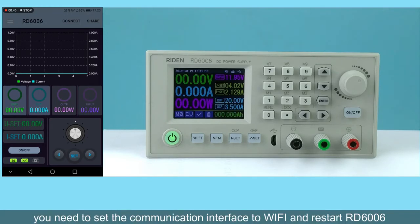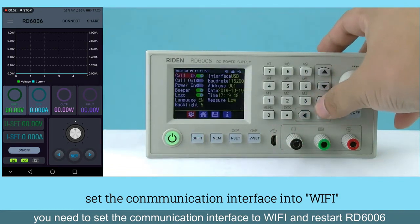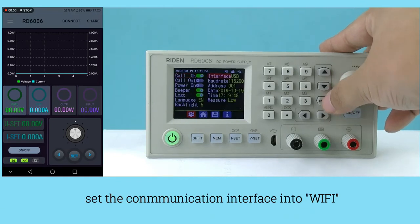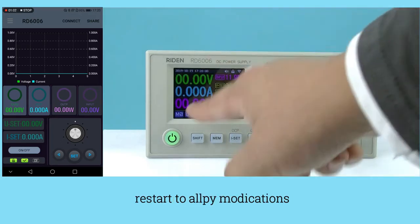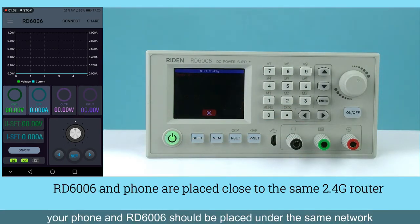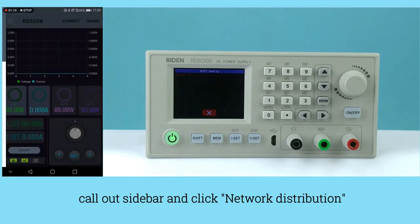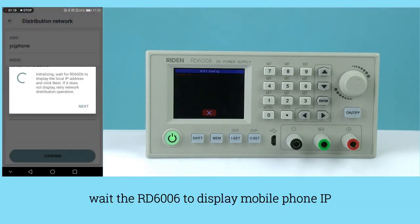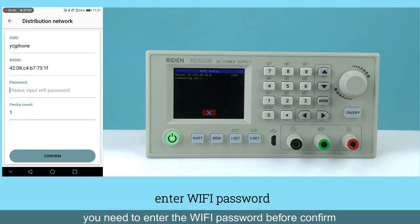You need to set the communication interface to Wi-Fi and restart RD6006. Your phone and RD6006 should be placed on the same network. Call out the set bar and click Network Distribution. Wait for the RD6006 to display mobile phone IP. Then click Next. You need to enter the Wi-Fi password before confirming.